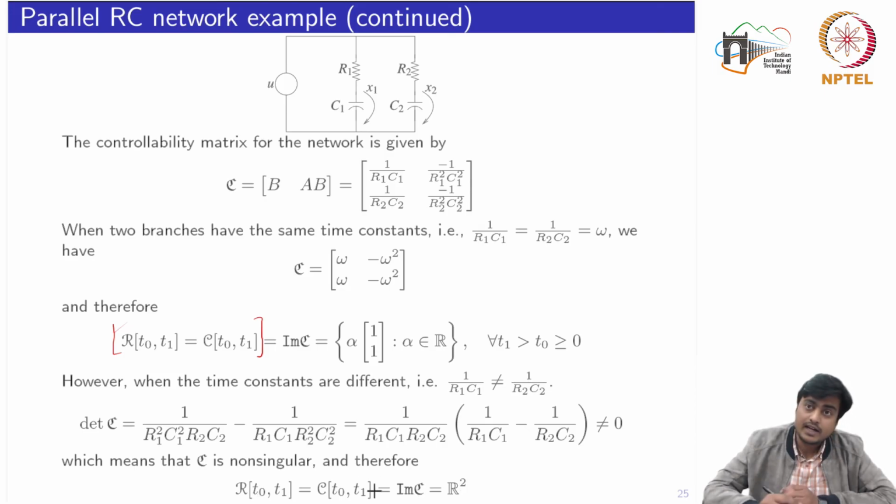So these matrices, the Gramian matrices for both the cases, LTV and LTI, and the controllability matrix, particularly for the LTI system, we could compute both these subspaces, which are quite important for the analysis of the controllability of the system. Okay.